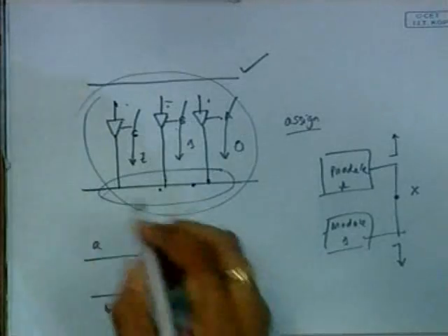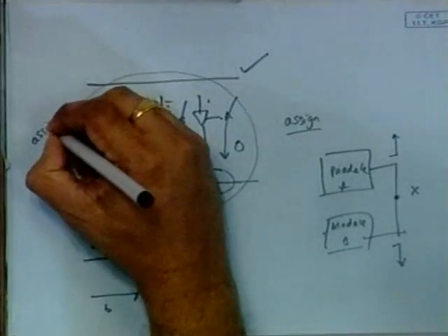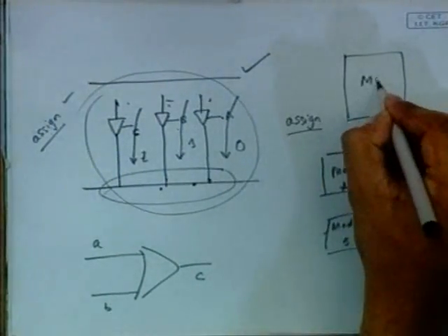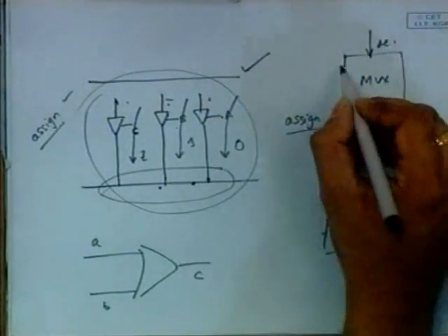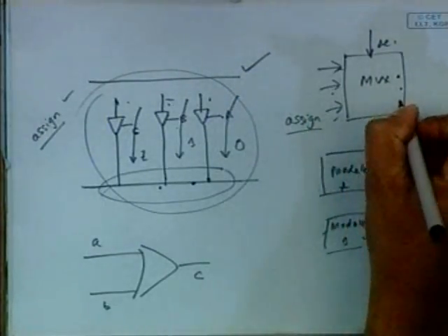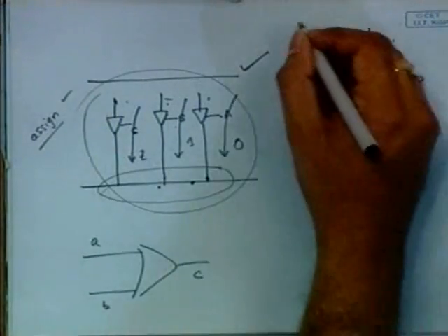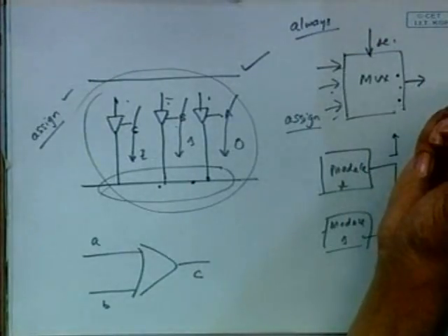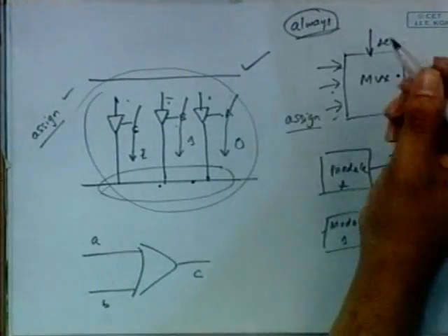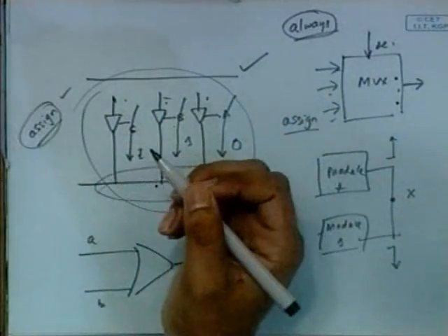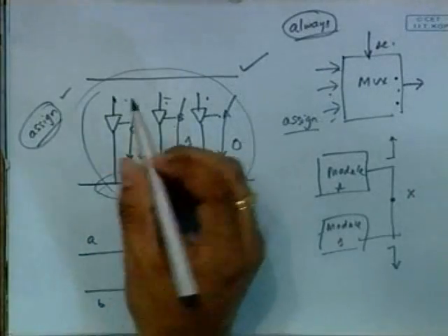So I may have a wire AND logic, a wire OR logic, and things like that, right? In this particular scenario, I would suggest you use the assign technique of coding. Whereas if you have a multiplexer in mind, where depending upon your select value some of the signals are being assigned, so either you choose this, or this, or this, in this scenario you use the always mechanism. Use the construct of always, and when you are describing a bus, you rather use an assign construct.